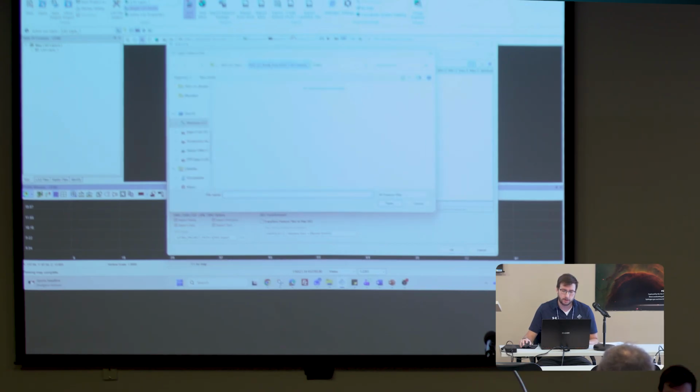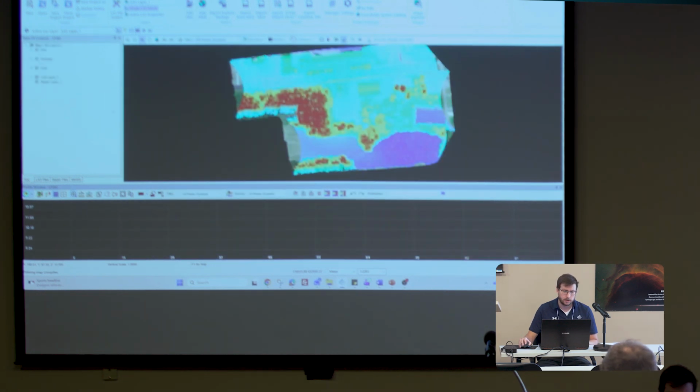Click on the feature tab to the right of the raster tab at the top. And let's just add all the features we were messing with yesterday. So this is curb, drainage, wall. We can go and add all those at the same time. And it's going to put those features on all separate layers when we do the import. So, yep, we should be good to go here. I'm going to click OK. So everything should be in there.